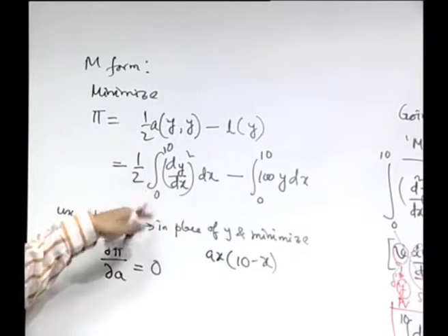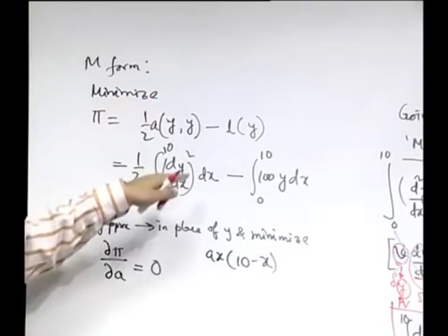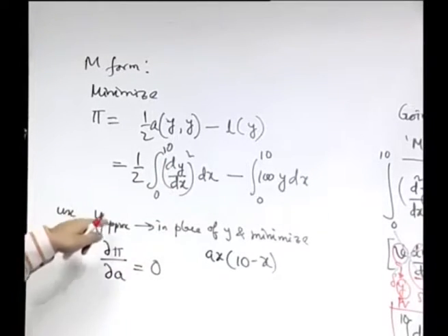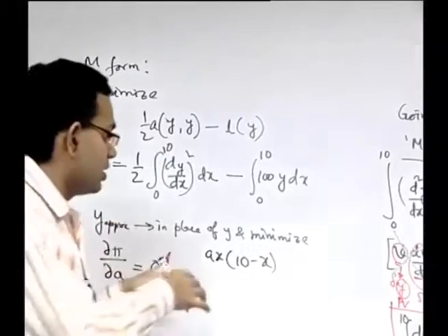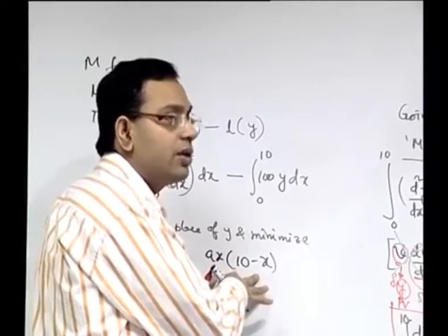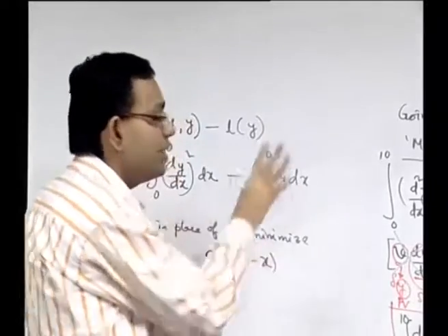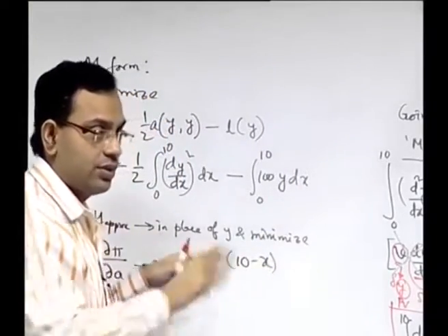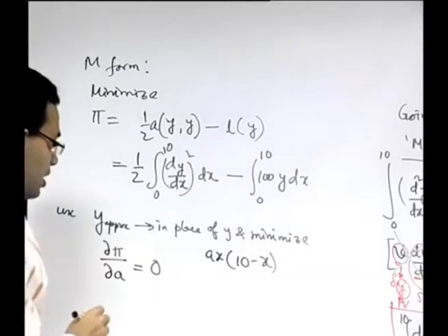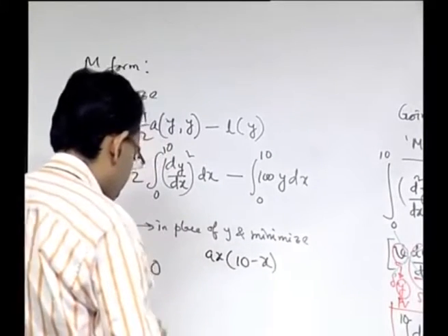A similar thing you can do for a fourth order equation, then you can come up with up to second order derivative. So, you can use approximating functions with reduced requirement of continuity, and no weighting function is necessary. That is one of the advantages of this method, and this method is known as Rayleigh-Ritz method.